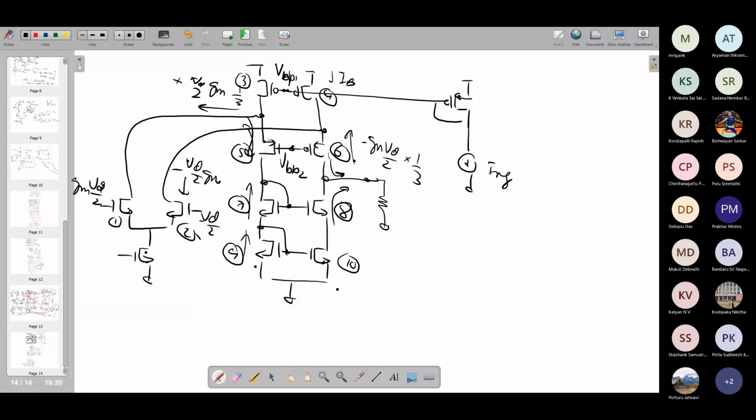The gate voltage VB2 is what we need to generate. For that, once again, we can pass the same bias current. So one option is that you can pass the same bias current into a similar transistor, which is, say, the same dimension as M4, and then you can have a diode connected transistor for, say, M6, and likewise two NMOS diode connected transistors at the bottom, which are also going to play a similar role as M7 and M9.